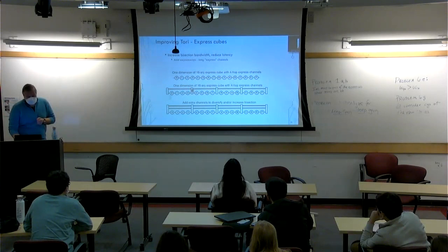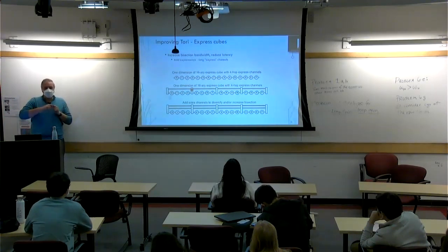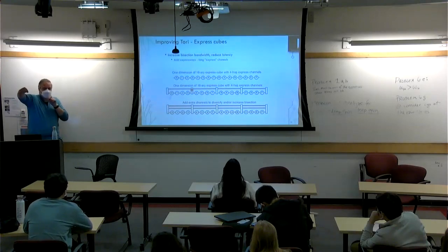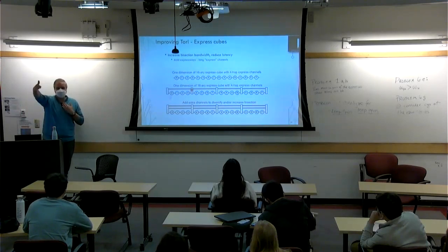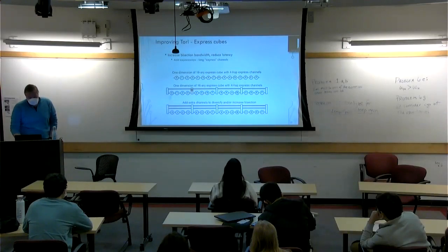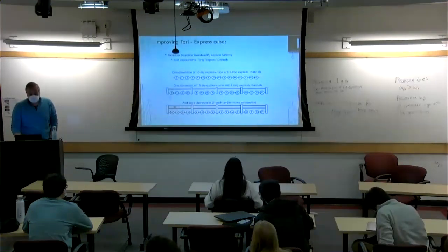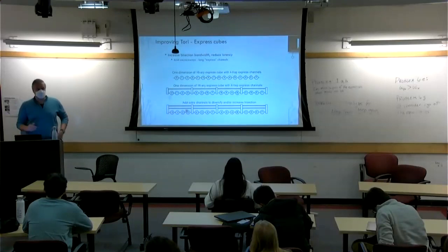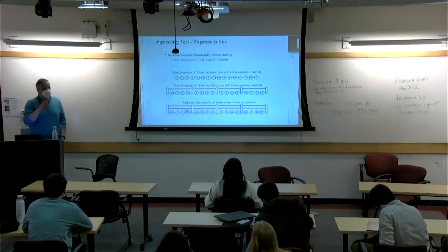But you can decide, for every 4 channels or every 4 routers, to add a bypass. So you don't have to wait to string along the whole dimension of the network to the edge of the chip. If you're going to number 4, boom, you immediately go to number 4. You don't wait 16 in line. You can add extra channels and make this spot faster than these spots, because this is for hyper traffic. It's an analogy of freeways and streets: freeways don't have that many exits, but they get you there faster.